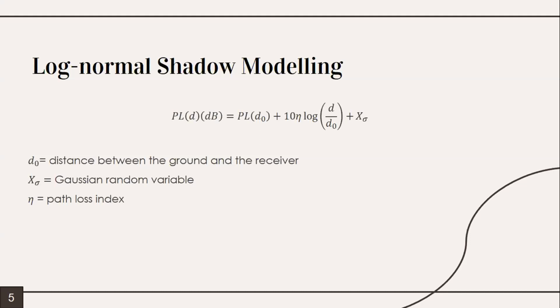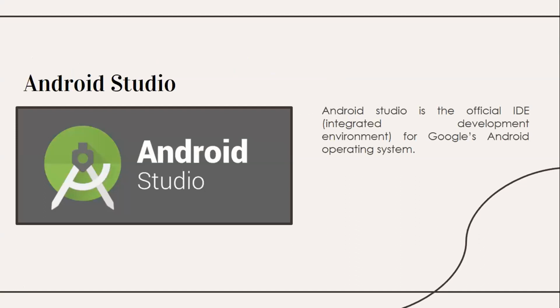The study area is going to be divided into several areas, and the determined RSSI value of each area is saved into the fingerprint of that area. Each area will compare the stored RSSI value with the RSSI value that is read in real time by the user. These features are displayed in the form of an application on an Android smartphone as the visual data interface. In this study, we are using Android Studio software to build the app.